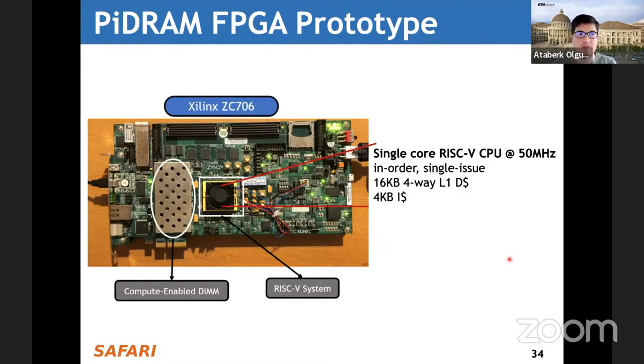What you try to do is find bank bits of the address by randomly generating addresses and testing if two back-to-back accesses to DRAM result in bank conflicts or not. If that's a bank conflict, you can tell because it will take more time than other requests. That way you deduce the bank address bits, and then later you can do the same again inside the bank, because now you know the bank bits, and you can understand the row bits and the column bits.